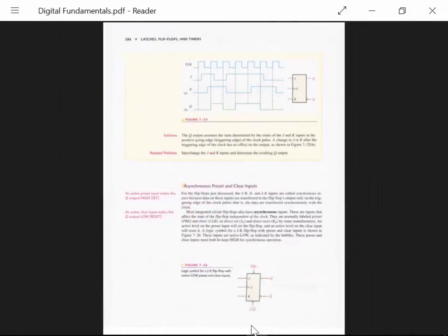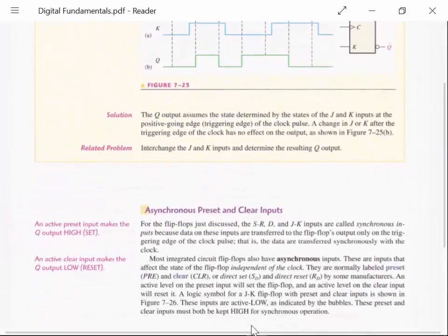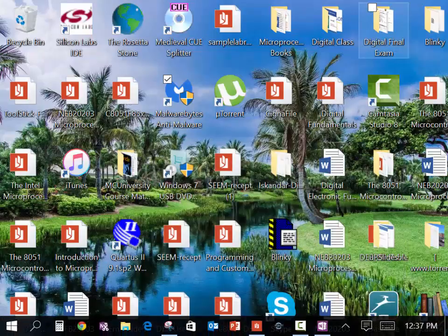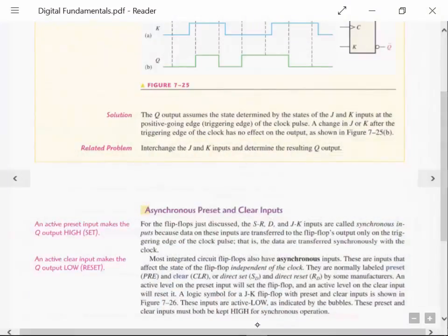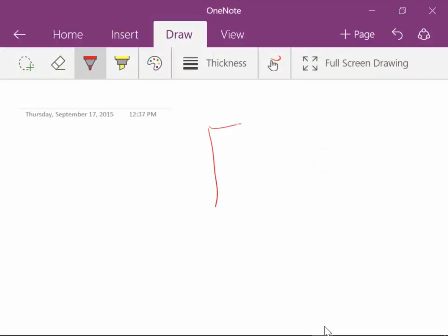sequential logic world. So the JK flip-flop, basically, when you look at it right there, and let me just go through again. When we look at the JK flip-flop, it has 2 inputs right there, J and K. We also have a clock input there. We have a Q out and a Q not. Later on, we'll see reasons why they definitely have the Q and Q not. Because as we build some of our circuits with these, quite often we want the Q not or the Q, depending on our circuit there.